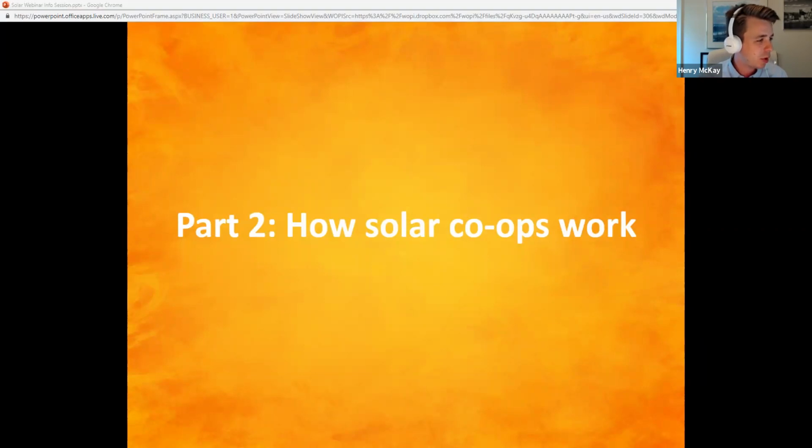We had a question from Lori, who asked, what is the ballpark figure for square feet of array versus kilowatts? The answer we typed in was that a typical 60-cell solar panel is 65 inches by 39 inches. That's about 17.5 square feet. Panels can range anywhere between 275 watts to 310 watts, often even larger than that for a single panel. So if you take the average 7.5 kilowatt system with a 290 watt module, that would be about 440 square feet of space. Of course, that number can vary a lot based on those assumptions.